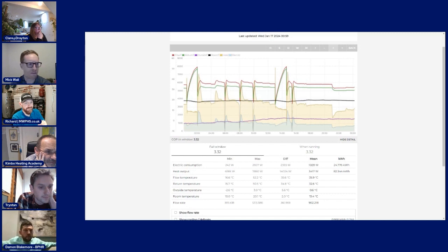On the Valent, you've got an option called Eco, which runs the compressor at about 50%. It's not a trickle, but it really scales back the compressor and puts the heat in a lot more slowly into the coil or the plate so that it can absorb it, and you use less electric to create that heat, so your performance improves. The only downside is that your run times are longer. So there's a trade-off, but I'm sticking with performance because I want to get top of the Scots, obviously.